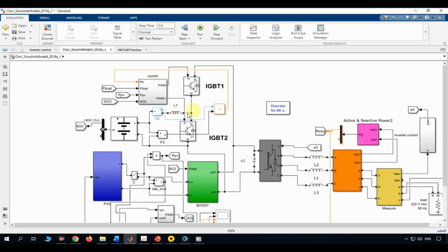This dialog box is where you tell Simulink exactly what battery you're simulating, not just a generic voltage source, but a real electrochemical model with capacity, internal resistance, and a discharge curve that actually sags the way a real battery does under load. In this video, we're going through every single parameter in this lithium-ion battery block, what it means physically, and how it connects to the discharge curves you see plotted on the right.